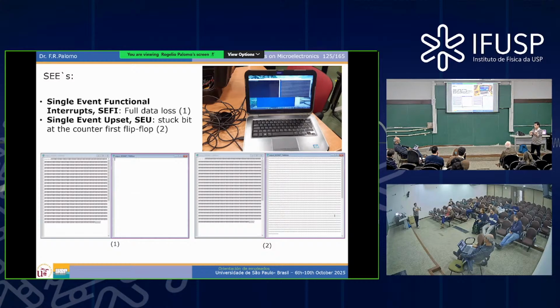No, I don't have the cross-section in that case, because this was not a characterization of the FPGA. That FPGA was characterized by Altera, and in particular, it has internal correction elements for single event upsets. That was one of the reasons to choose precisely that, because Intel was selling the product for space. Any product in space needs to have EDAC, systems for correcting errors. And for sure, in the static RAMs in the FPGA, the EDACs were working perfectly.